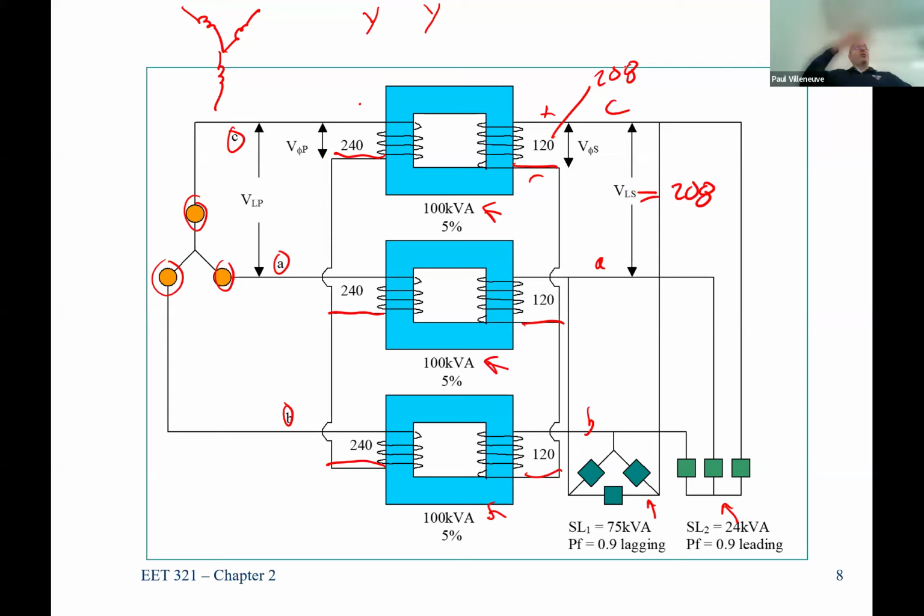You've got this super duper lathe that can do all these fancy things. And you go to plug it in and it needs 3 wires and you've only got 2. It doesn't work. So you have to change the motor out, or you have to put a phase converter on it, which is very expensive. So be mindful that most of the time, if you're doing woodworking, you need to be very careful. And it's only because the motors, once they get big enough, you have to get 3-phase motors. They're just not practical to get them cheap.